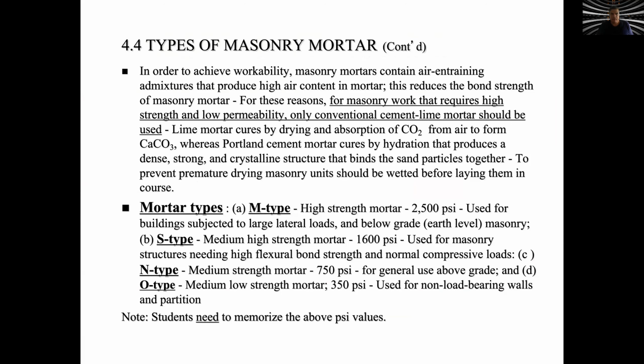There are many types of mortars, and it depends on the materials and the proportion of the materials between them. Usually in order to have some workability, we will have some mixtures that will allow a higher content of air in the mortar, which is not so good for the strength of this material, but will allow us to work with it better.